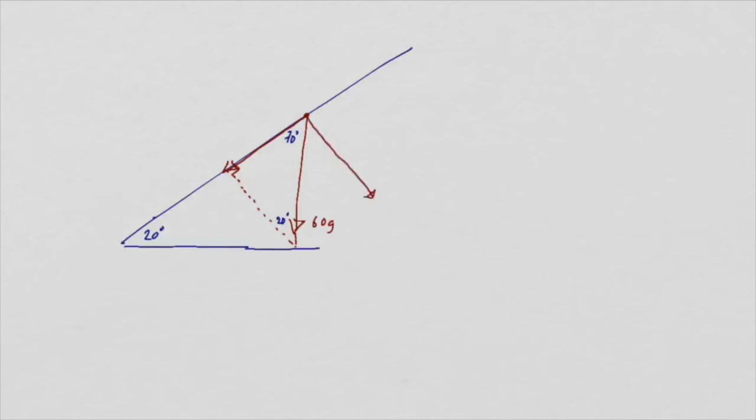so they look like that. But if we put a dotted line across there, so that's parallel to the plane, then that length I've just added dots to is the same length as our perpendicular force. So now we'll give these two components names. That one we'll call F parallel, that one F perpendicular, and then we can draw a triangle separate from the diagram to represent the situation.